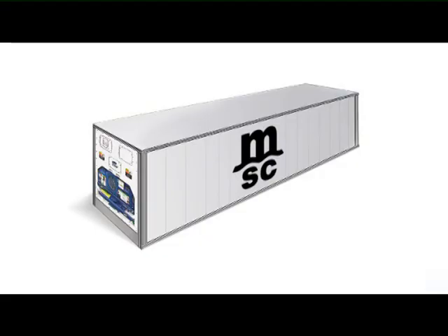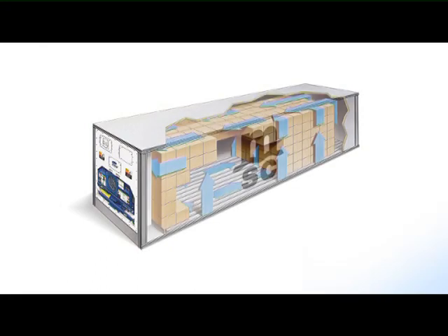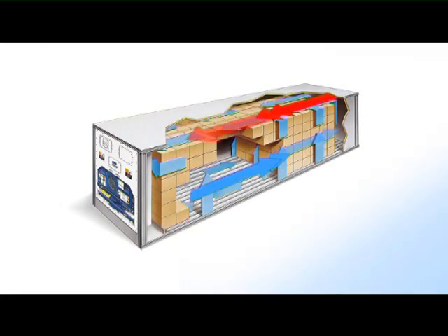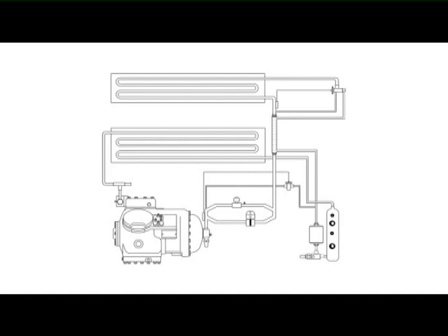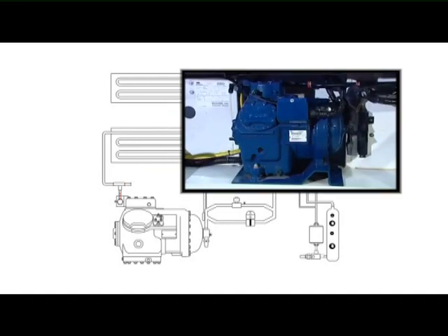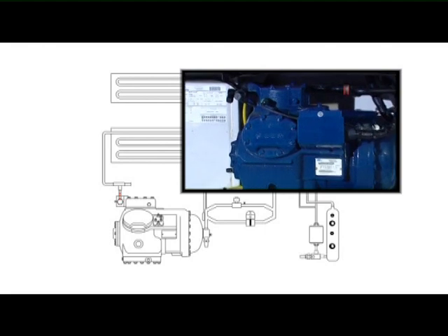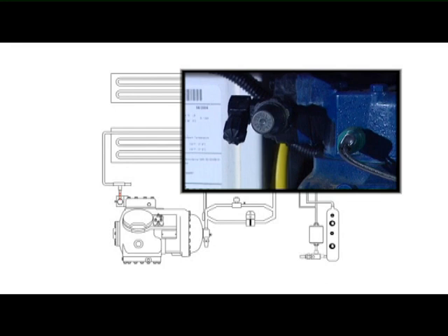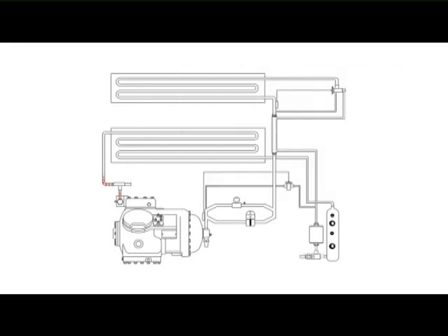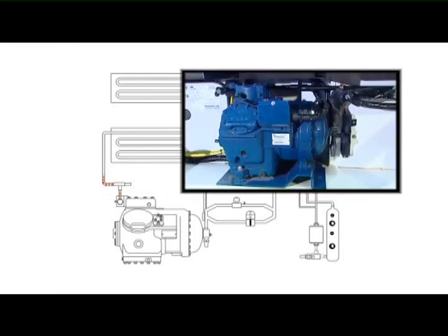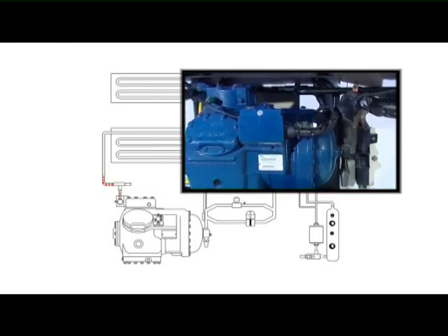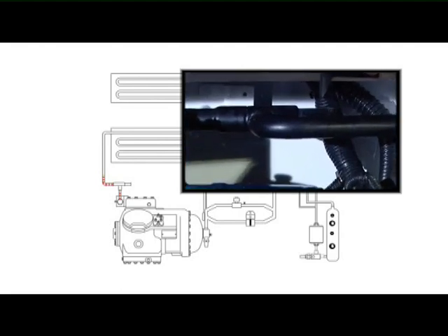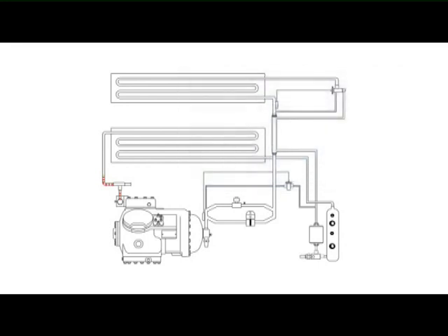Refrigeration cycle. The refrigeration system absorbs the heat of the cargo at the evaporator and rejects heat at the condenser to the ambient air. Starting at the compressor discharge service valve, the high-pressure, high-temperature superheated vapor passes through the discharge line to the discharge pressure regulator. The discharge pressure regulator ensures that the discharge pressure never drops below 5 bar. This is necessary to avoid the suction pressure reaching the vacuum that could result in oil foaming and loss of compressor lubrication.